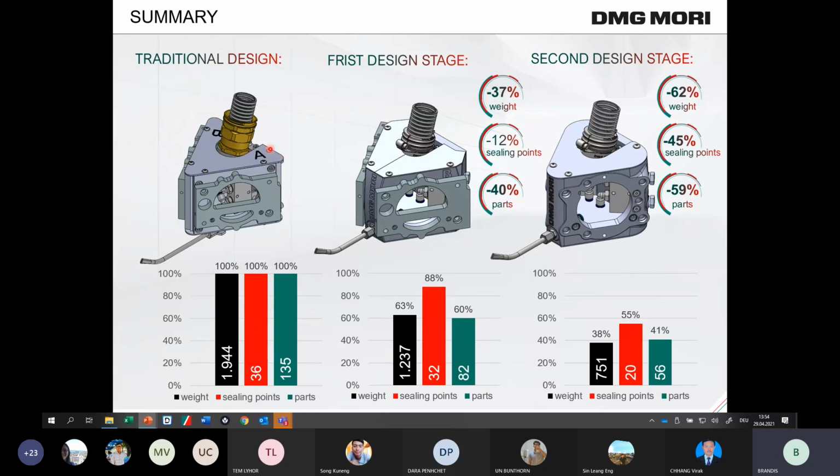So we have three milled plates assembled together, and this makes it very difficult to get a high accuracy of the two grippers. So if you want to pick a part with gripper A and then you rotate your robot head to gripper B, there's a lag between position A and B.